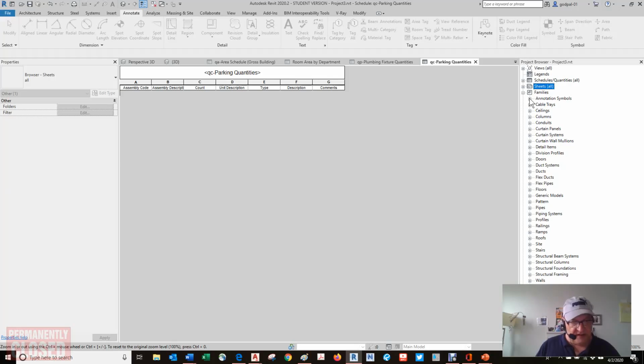The project browser can also be filtered and grouped into folders based on a number of user-defined parameters. To access the project browser properties dialog box, click the Views portion at the top of the palette. You can also access this tool in the View tab under the User Interface Flyout button. Learn more about project browser customization in Chapter 4.